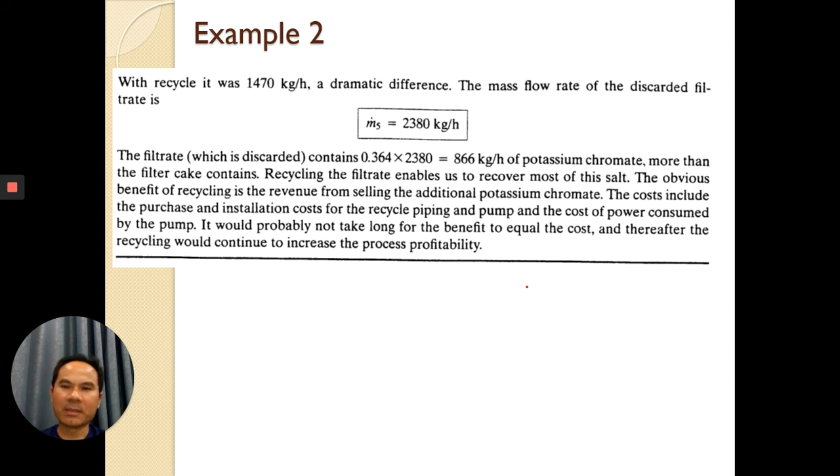Okay, looks like this. But the cost is also there if you drop the recycle. If you drop the recycle, the cost does not include the purchase and installation cost for recycle piping and pump. You have to check if you recycle, and then you compare the costs.